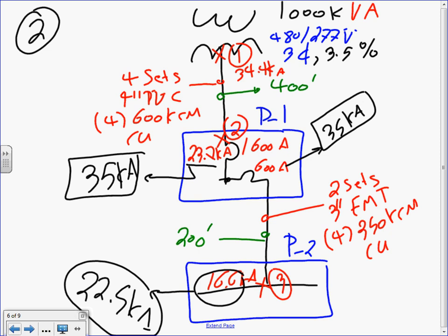The second one is phase to phase. Instead of three phases together, you take phase A and phase B, bolt them together, and flip the switch. That will typically give you 87% of the value for the three phase. If you cover the 100%, Darren, would you worry about the 87%? You already covered it. The worst scenario is covered. So phase to phase is typically 87%.